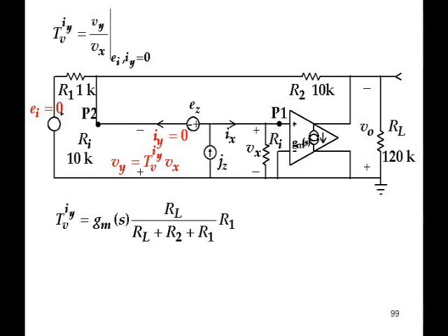That's a divider with RL on the right and R2 plus RL plus R2 plus R1 on the left. And VY is the voltage across R1, so R1 is the final multiplier. Again, simple, single path, straightforward calculations invoking the fact that the null exists. Very easy to do.